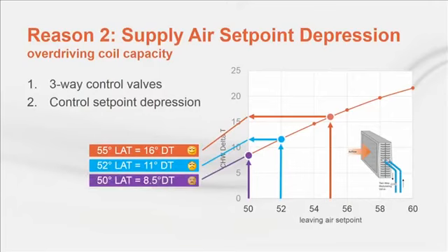Tomorrow's result? A full load delta T of 8.5 degrees, requiring almost double the design flow, if the pumps can produce it, and close to 8 times the system pumping energy. Based on my experience and case studies I've read, this is the number one ongoing cause of excessive low delta T. Coil control set point discipline is critical in the maintenance of system delta T.